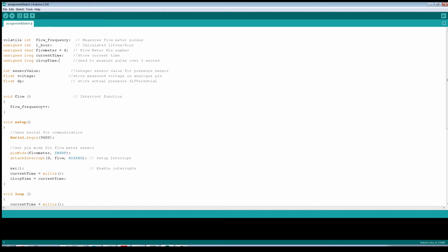Each time we have a pulse, we know that approximately a certain amount of fluid has flowed through our device. So what we have to do is define a time period, and we count the amount of pulses over that time period.